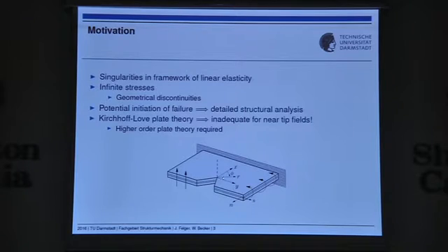Due to these high localized stresses here, the classical Kirchhoff-Love plate theory is unable to render correctly the asymptotic near-tip field, which is basically due to the kinematic assumption, and that's why higher order plate theories are required.